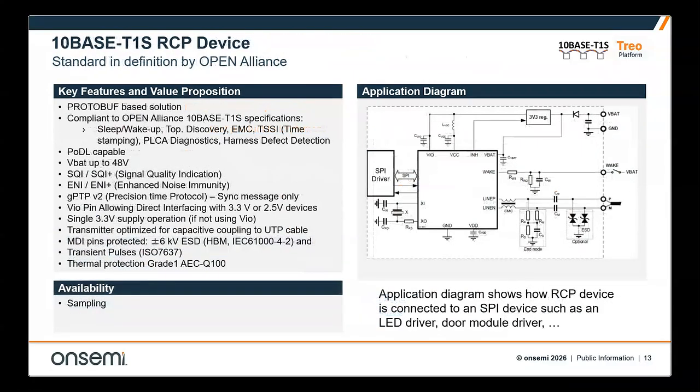So now let's introduce our RCP device, arguably the most disruptive product in the 10BASE-T1S portfolio. This is designed for edge nodes that need full network connectivity but should not need a local microcontroller. So that's a fundamental shift in how you architect a vehicle network. The protocol is protobuf based and is being standardized through the Open Alliance, and the device is fully compliant with all the key specifications.